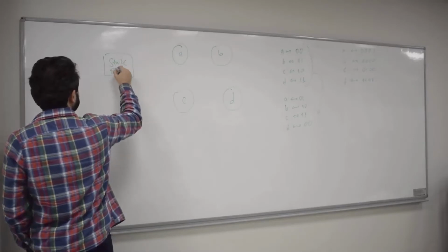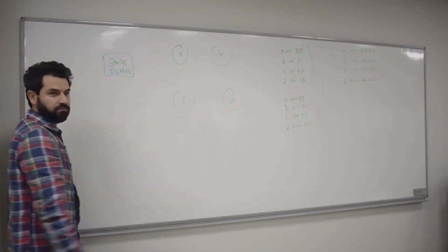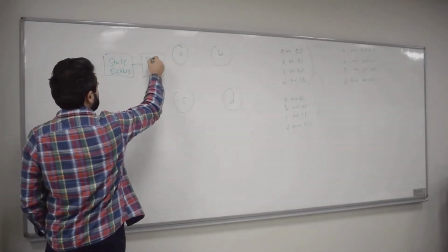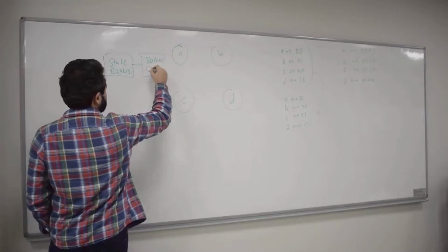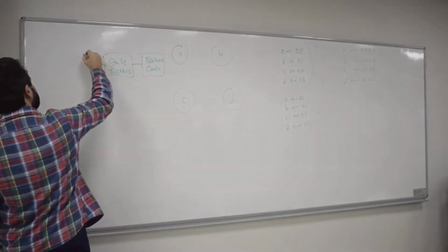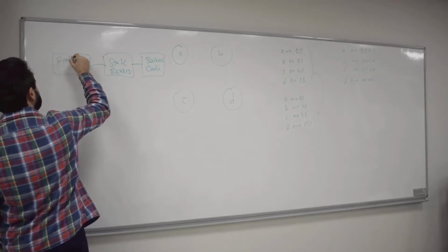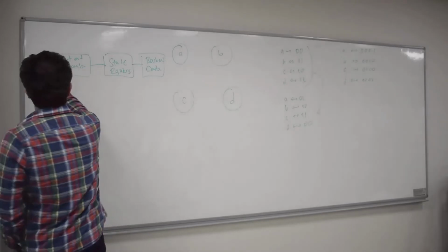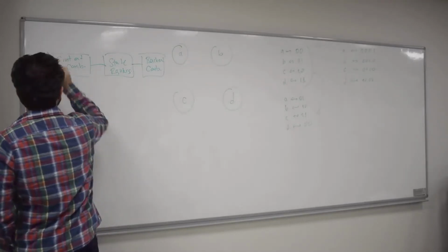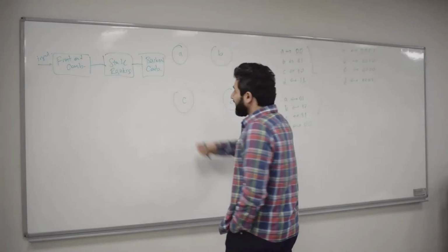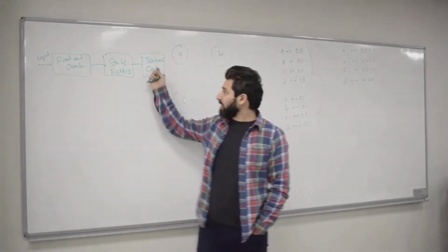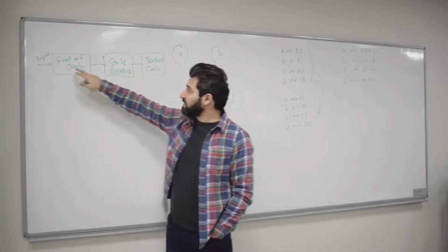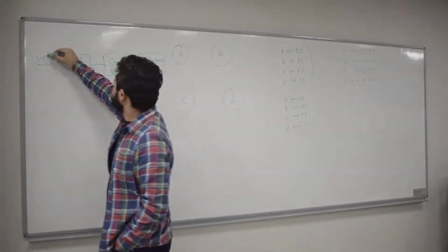State registers. These are flip-flops, by the way. I call them registers. And there are a front end and a back end, right? For example, this is the back-end combinational circuit, and there is a front-end combinational circuit. Remember them? And we said that this is the input, right? And this back-end combinational circuit can use, has to use, the state register output values as well as the input. It can use them.